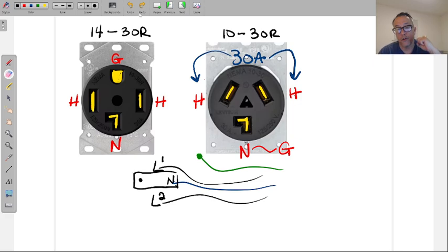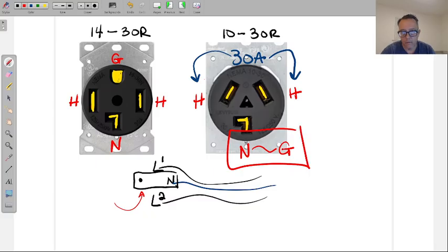If you are going to use the 3-wire, you are simply going to remove the whole cord and then install your 3-wire and leave that little piece of metal connected to the frame, because your neutral is also your bond for the frame.